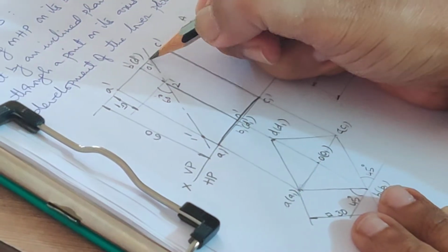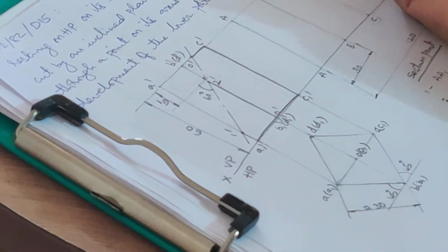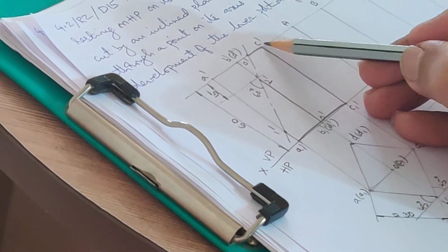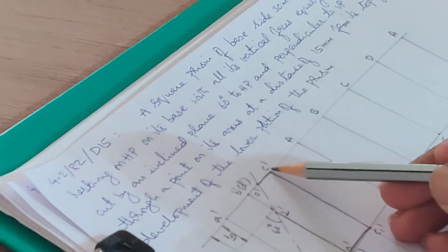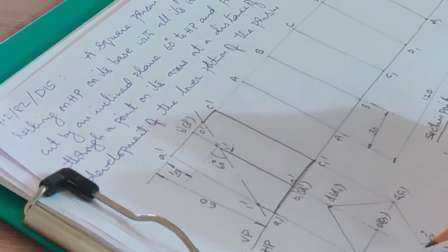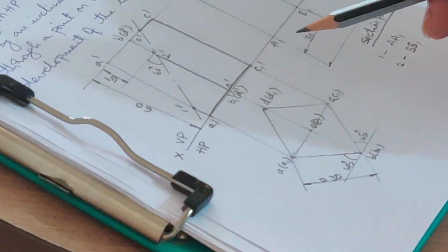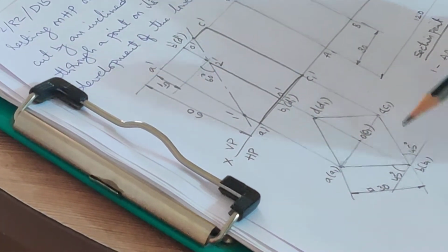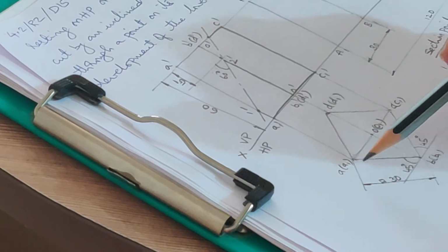Then move ahead, you come here. Yes, this is in fact cutting the base itself. When it is the base, you have 4 base edges as you see in the top view. So you don't know which base edge it is cutting. There are 4 base edges at the top face, AB, BC, CD and DA.